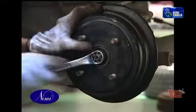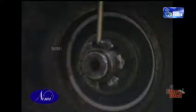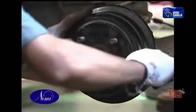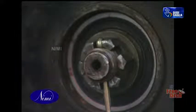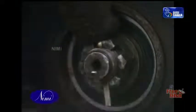Split pin. Tighten the nut at the specified torque. Check the bolt's hole and nut's slot alignment. If not aligned, align the hole by tightening the nut slightly. Insert a new suitable split pin in the slot and hole. Drive the split pin fully inside. Spread open the sides of the split pin and bend it on the nut.